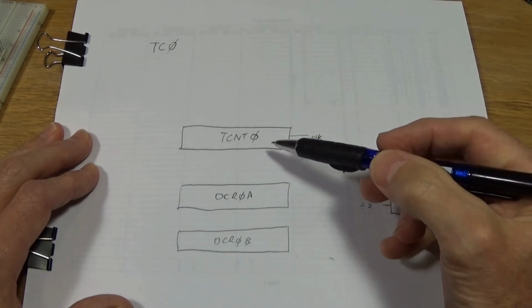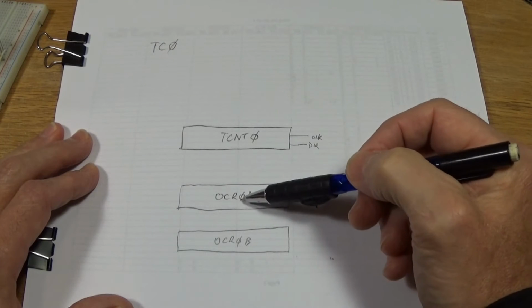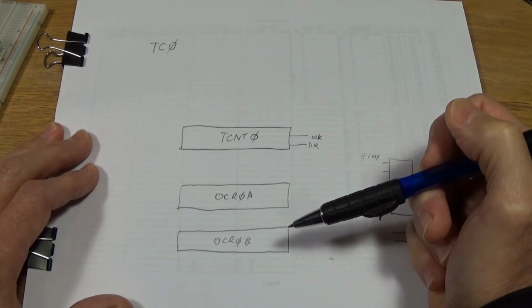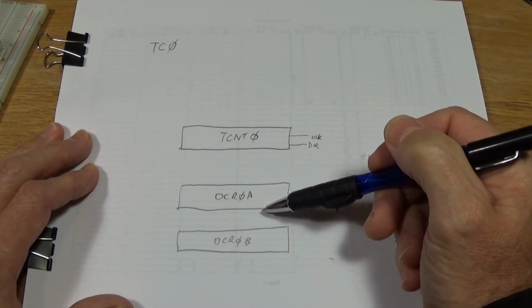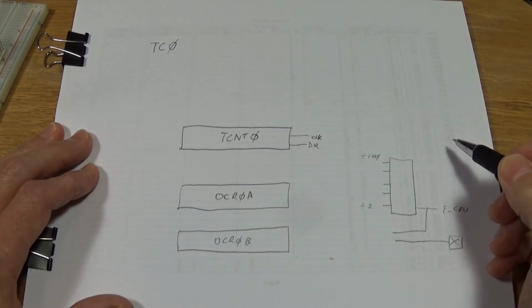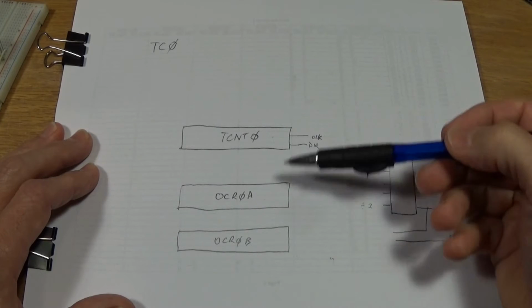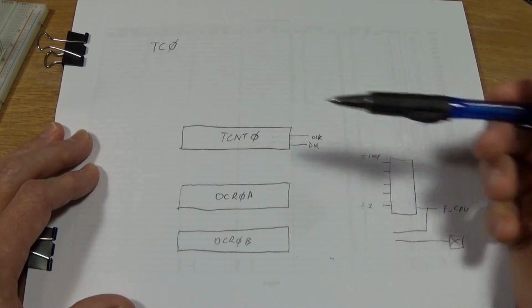So what's going on? There's logic that connects these two registers with the timer counter register, and it's constantly comparing this register with that and this register with that. And when they get a match, you get a signal. You get another flag set, an interrupt flag, and it's called the Output Compare Match flag. So there's a source of 3 different interrupts that you can generate using this timer counter.